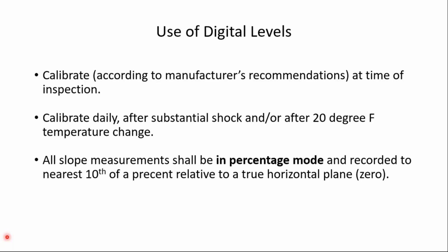I'd recalibrate it. And also, especially in the spring and the fall of the year, here in the East or Midwest, a cold front may move through, and so it may have been in the 60s in the morning temperature-wise, and it's maybe in the 40s or 30s by the end of the day. Probably not a bad idea to calibrate the level again.